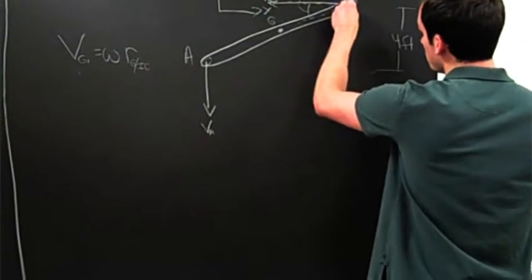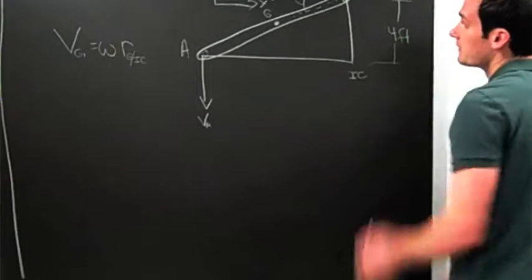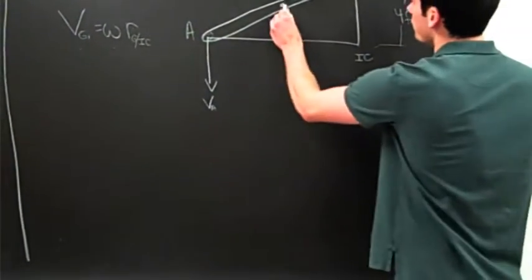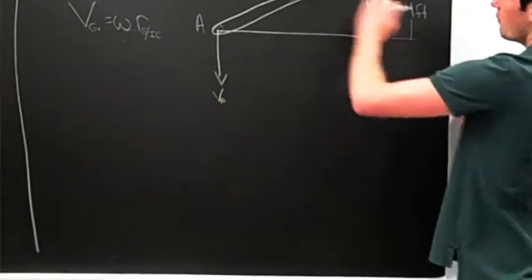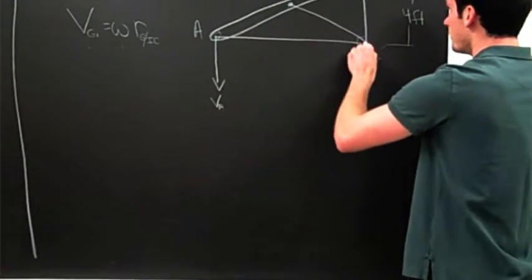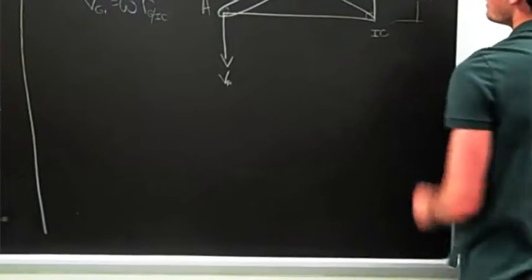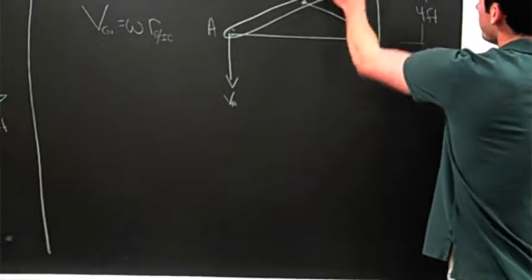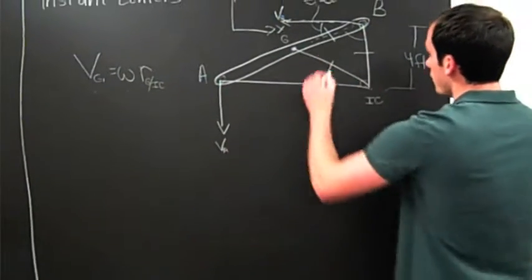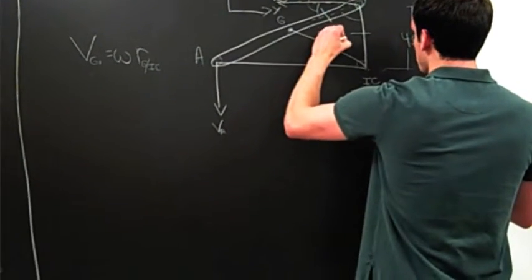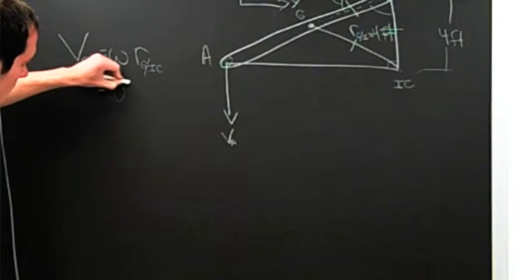And so from that, we also know the radius, which is 90 degrees, is going to go down for this one and to the left for this one. So this is going to be our instant center. We already know this is 4 feet. For the center of gravity, since this is a smooth plate, we know that the distance from G to B is also going to be 4 feet. I'm going to move this over here. And this is a right triangle. The center of gravity, since this is all one piece, the radius to the instant center is going to be right down here. So we have 4 feet, and since this is a 30, 60, 90 triangle, this is 60 degrees. And since we know some geometry, when you have two sides that are the same length and the angles are the same, these sides are all going to be the same length. So we know the radius from G to the instant center is also going to be equal to 4 feet. So now if we go over here, we have V of G1 is equal to omega times 4.